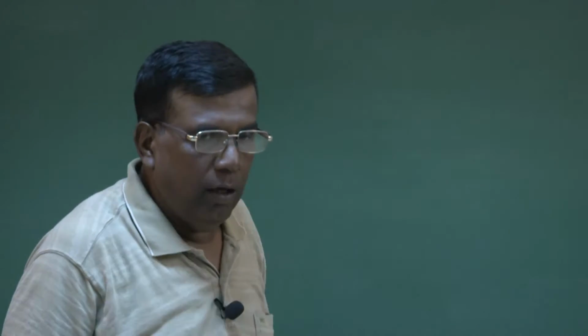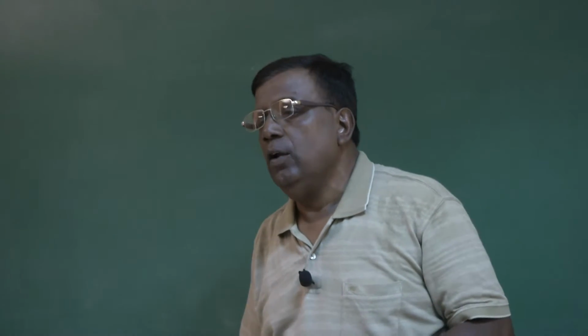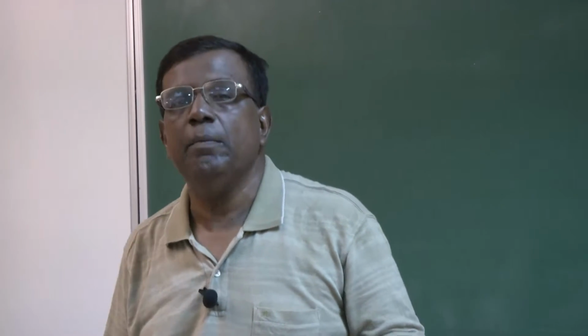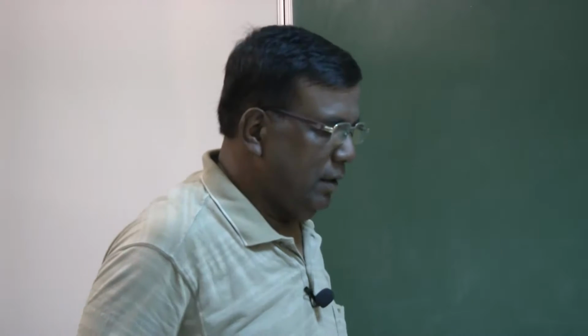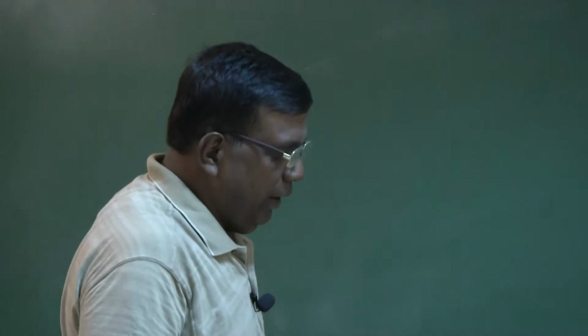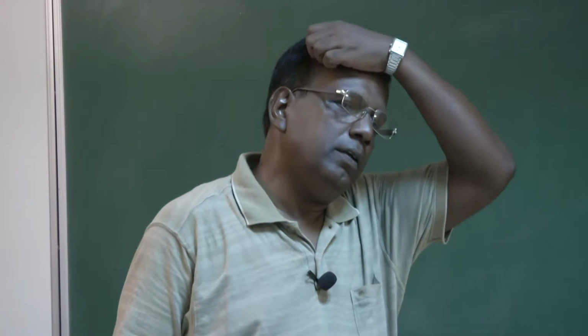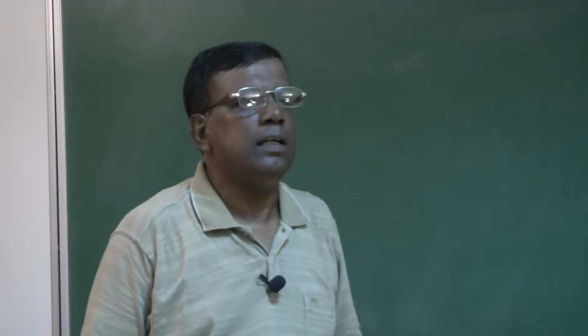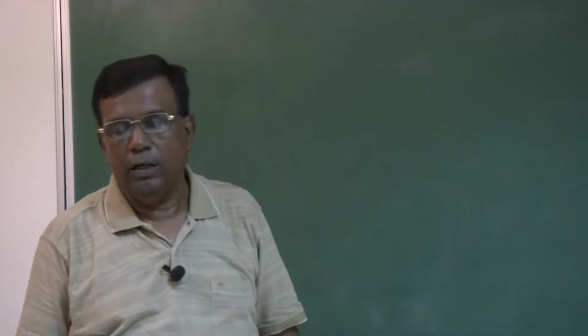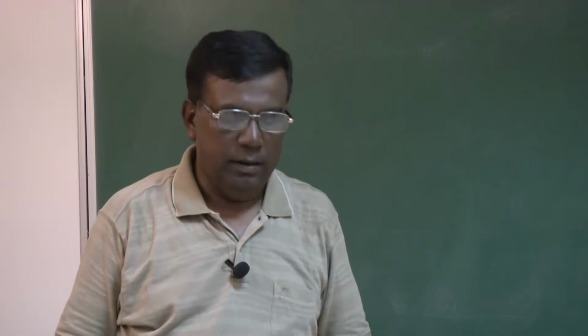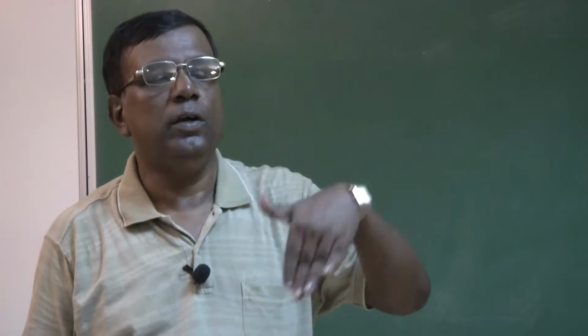Yes, dear friends, now we have gone one more step and we have seen, for a mass spring damper system of second order in nature, how to analyze it and what mathematical background or technique is required to find out the damping ratio and natural frequency. It is more important to make our understanding very clear that a second order system need not oscillate. It will oscillate, or it will return without oscillation.